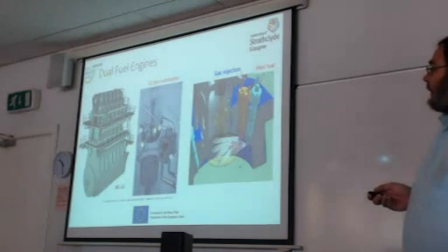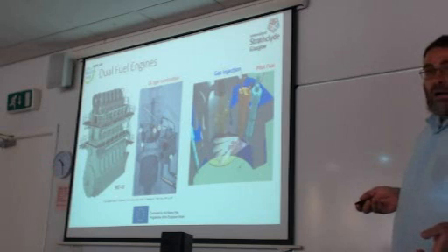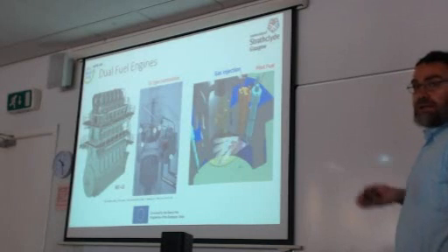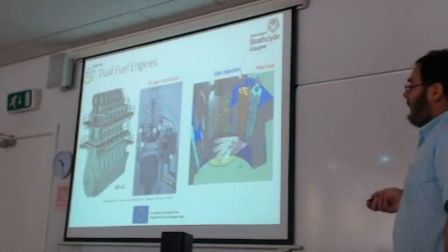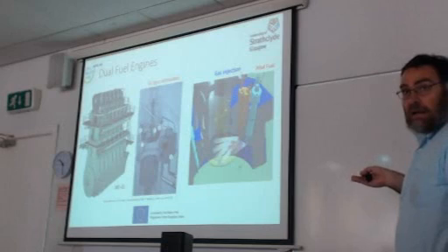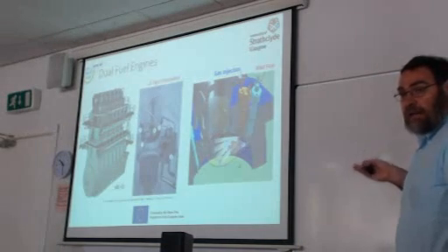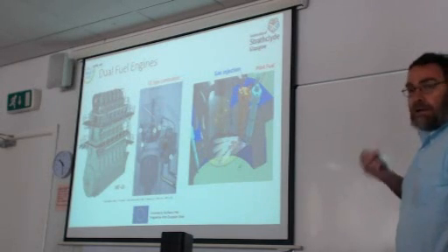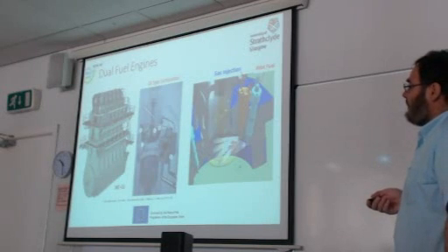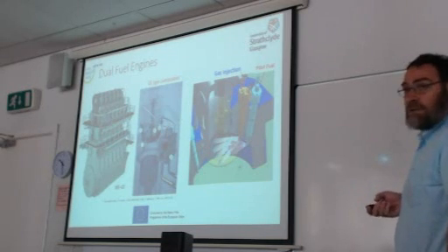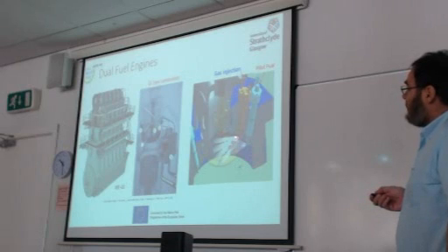So, the alternative or the competitor in two-stroke engines is the gas ignition type engines from MAN Diesel & Turbo. In this case, of course, the two-stroke engine is the most common type of engine installed on board large ships, as prime mover, and heavy fuel oil is needed. Actually, this type of engine can burn every type of fuel independently of the quality. And of course, cheap heavy fuel oil is used.